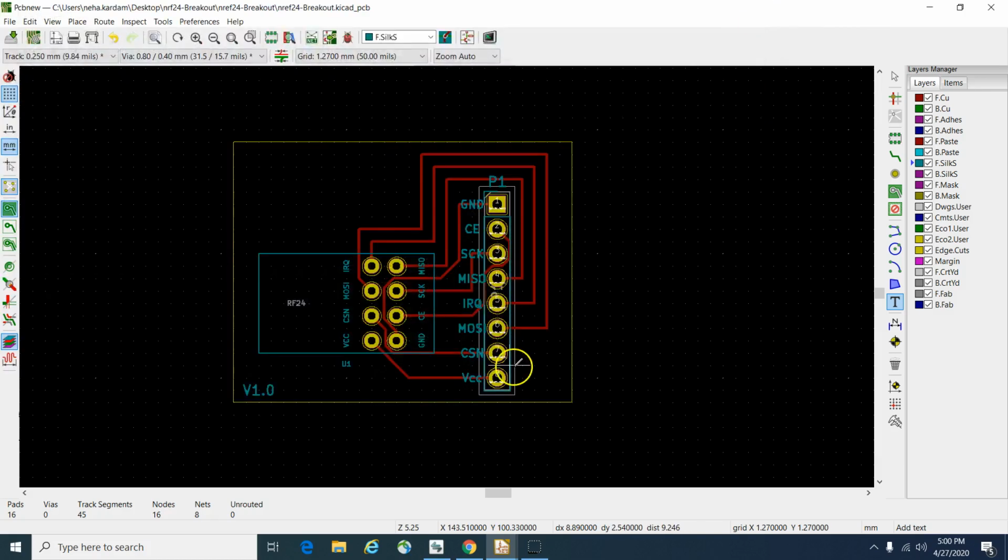Now, the other thing which I did on my circuit is to add the version number. Since designing a board is an iterative process, it is a good practice to have a version of your board before you send it for manufacturing. This way you will be able to tell them apart, especially if the differences between subsequent versions are small.